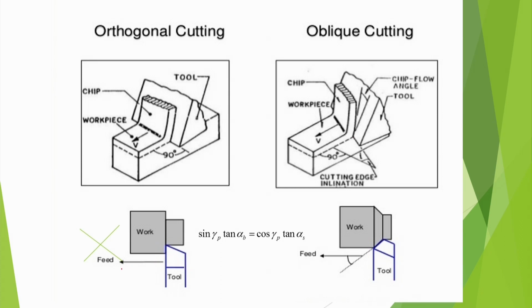They say that in a lathe machine, if the tool is moving like this, this is orthogonal cutting, but actually it should not be the correct definition. In fact, this type of turning operation is not orthogonal at all unless you are machining a tube, because in orthogonal cutting another condition is that the tool edge should extend beyond the job also. Many people say okay, this is pure orthogonal cutting and I will call this also orthogonal cutting, but many books will not agree to this. So you have to be careful.